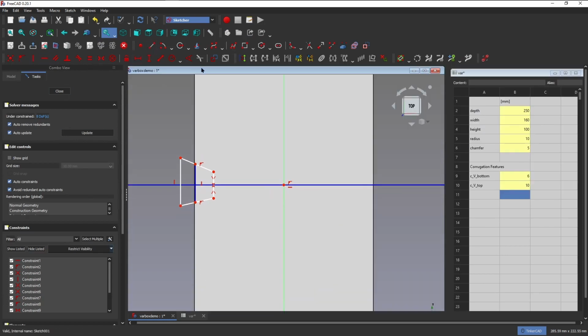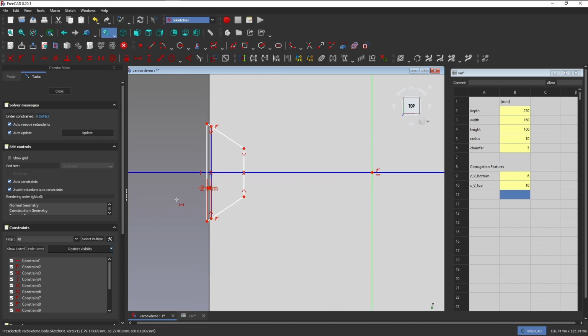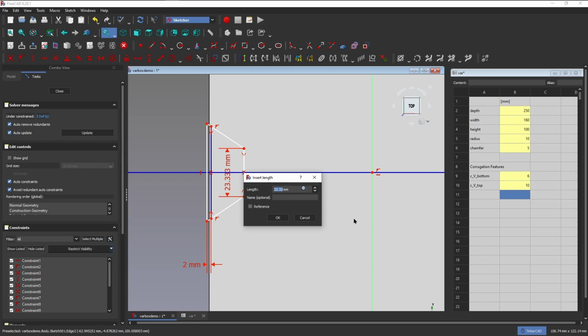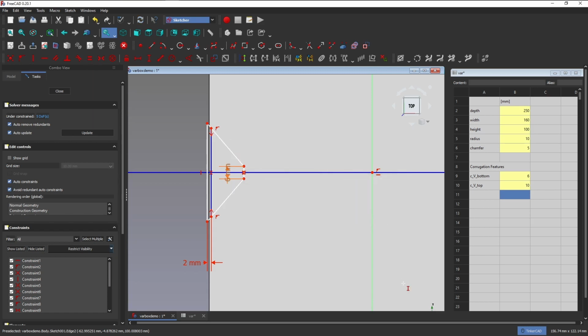and we're going to create symmetrical for this feature and that feature to the line. I want to constrain this not because it needs to be constrained, but because constraining that will prevent us from having problems. If you scale models that are not fully constrained, you can have stuff break unexpectedly. Go back in here, far. This is the bottom. Enter.